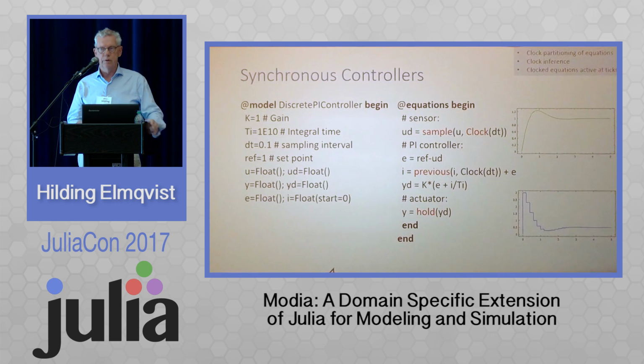We are working also on synchronous controllers. It's a special semantics for how to couple control systems in a safe way to physical plants. I will not go into details. I just want to mention that this is also done. And then you need to infer also the clock. So each variable and each equation has an associated clock, and you cannot mix them in an arbitrary way. So it's actually checking that the variables and the equations have consistent clocks. That is also done in Modelica, so it's nothing new. We are re-implementing this now.